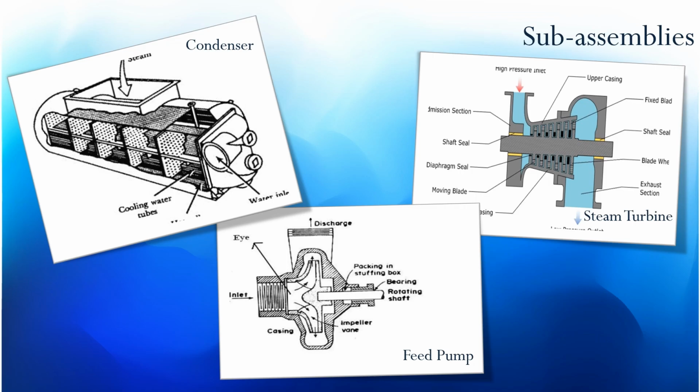The last step of the cycle is for the water being recollected to be sent back into the reactor to be used again. This is accomplished using what we call a feed pump. The feed pump raises the pressure of the water in order for it to overcome the pressures within the reactor. Now that the water is back in the reactor, the cycle can continue.